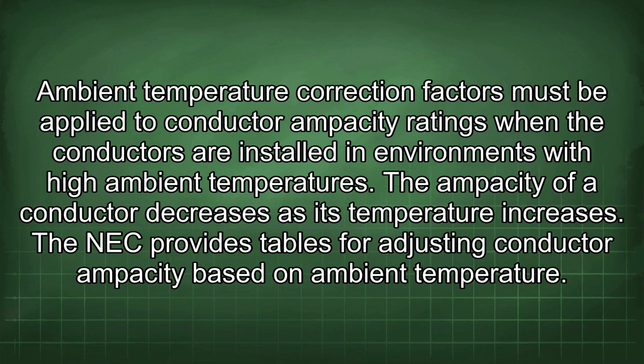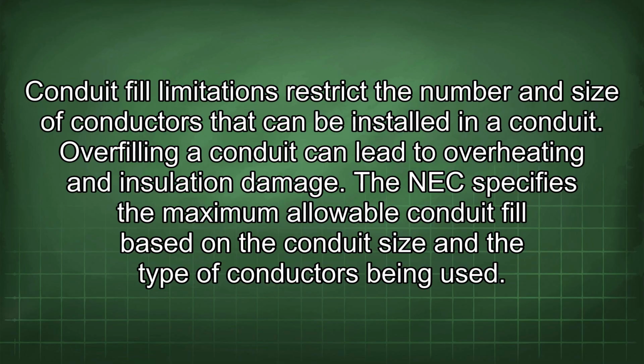Ambient temperature correction factors must be applied to conductor ampacity ratings when the conductors are installed in environments with high ambient temperatures. The ampacity of a conductor decreases as its temperature increases. The NEC provides tables for adjusting conductor ampacity based on ambient temperature. Conduit fill limitations restrict the number and size of conductors that can be installed in a conduit. Overfilling a conduit can lead to overheating and insulation damage. The NEC specifies the maximum allowable conduit fill based on the conduit size and the type of conductors being used.